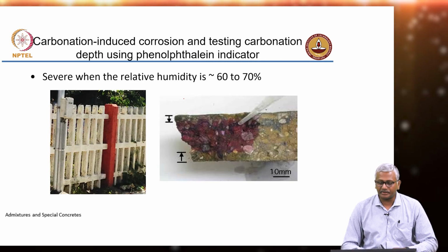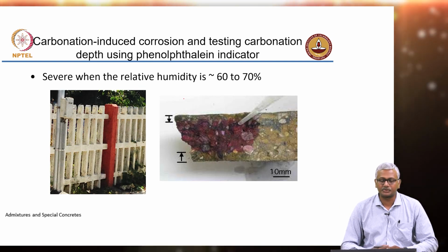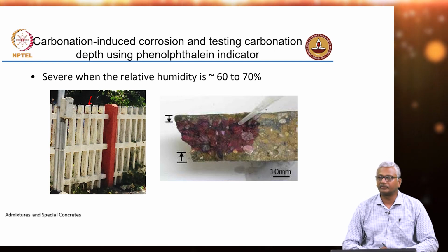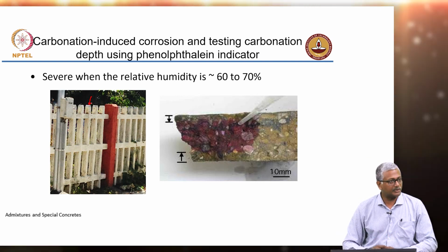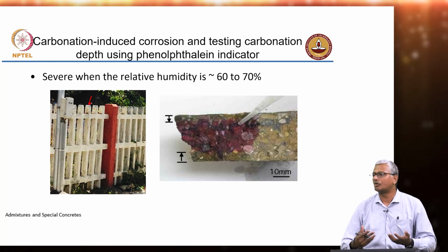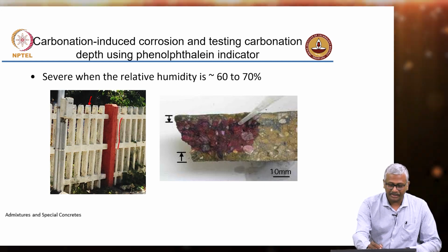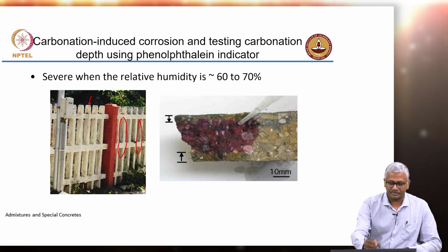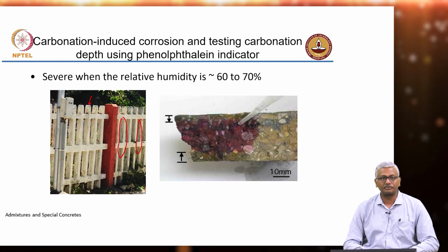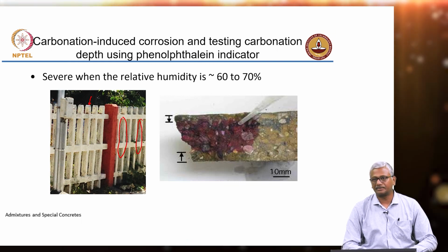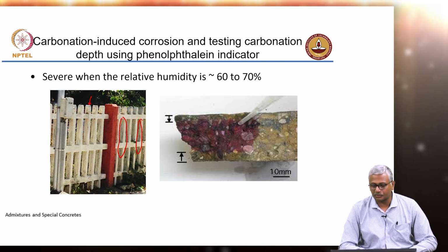So this is a typical case of a carbonation-induced corrosion. You have very thin members, thin reinforced concrete members. So it is not going to take long for the CO2 to penetrate to the extent of the steel, and if there is rainfall that provides moisture, you will definitely get corrosion that leads to cracks like this. So this is a telltale sign of corrosion. Okay, all along the steel there is cracking. That is a very clear sign of corrosion happening.